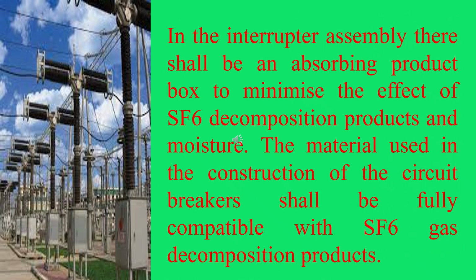In the interrupter assembly, there shall be an absorbing product box to minimize the effect of SF6 gas decomposition products and moisture. The material used in the construction of the circuit breakers shall be fully compatible with SF6 gas decomposition products.